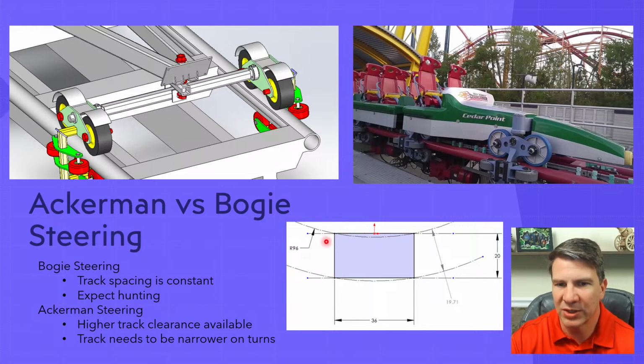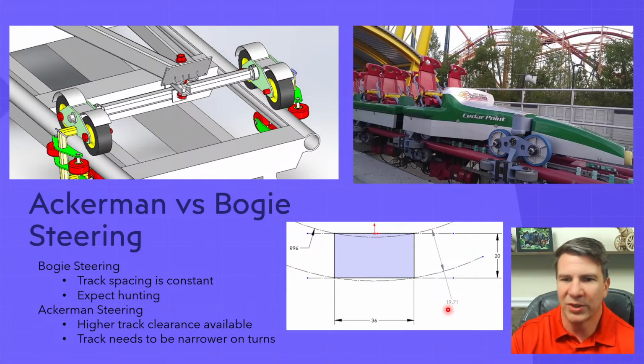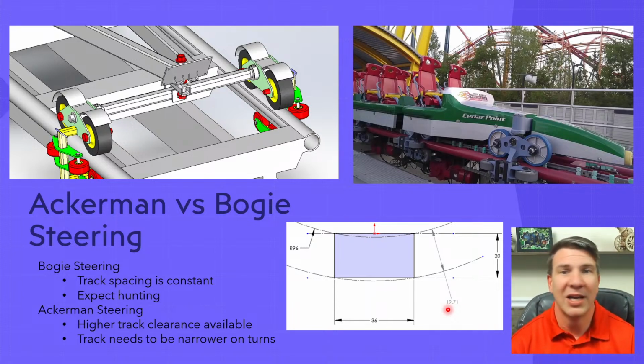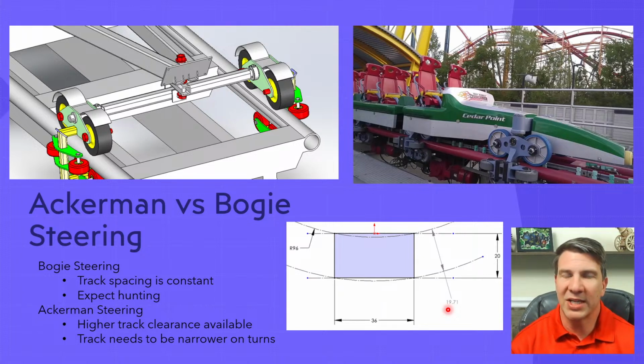But when I go into a corner, I now need to make my track 3/8 of an inch, or 0.3 inches, less wide than I do on a straight track. And that gets into a fabrication nightmare for me. I just don't want to be doing that. I don't have the tools for making it accurate enough to do that. But I can go on there with a 20-inch fixture or even a tape measure and say, okay, this is 20 inches apart. That's where I need to be. Let's make it work there.